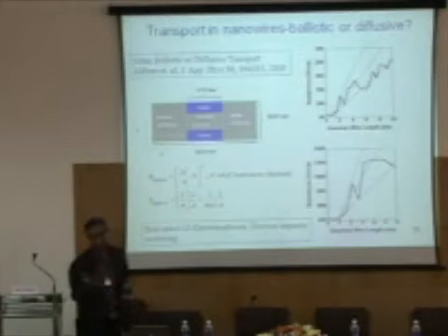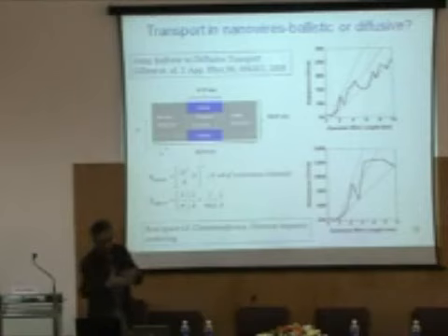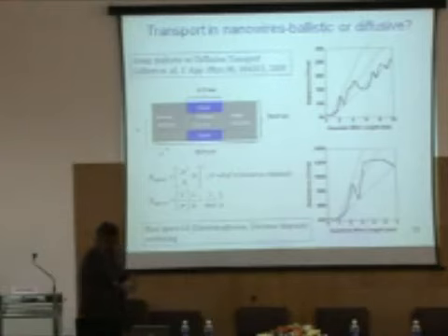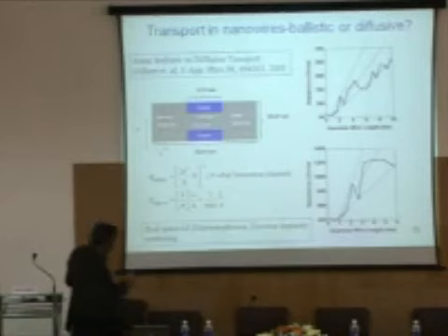To do theory, I must understand whether transport is quantum transport or ballistic transport or diffusive, where the electron moves, scatters with phonons, there's a mean-free path, and then whether the nanowire diameters are large or small compared to the mean-free path, so I have to worry about those. So one calculation which was done nicely recently is taking some actual good calculations, taking some sort of channels, transistors. If you think about silicon channels, oxide barriers,